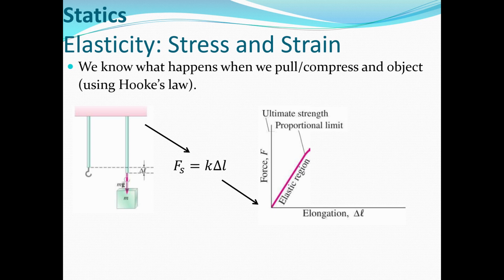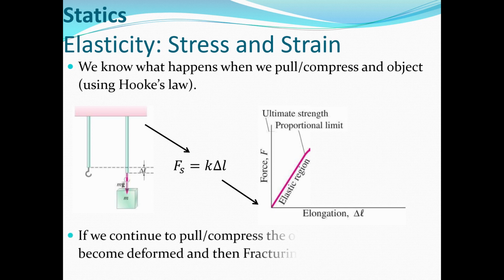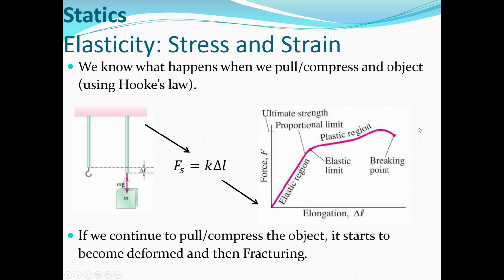Now, anyone who's ever played with a slinky knows that when they stretch it, the slinky comes back to its original spot. But once you extend that spring past a certain location, it technically never goes back to its original spot. There's an extension to this graph that deals with what's called the plastic region.